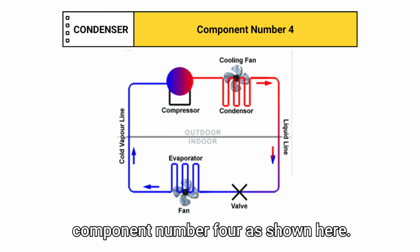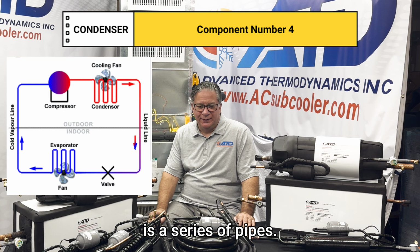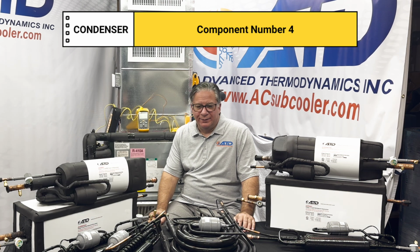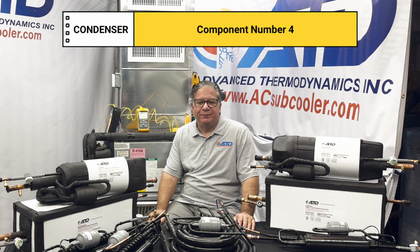The condenser, like the evaporator, is a series of pipes. Outside air is blowing across the condenser pipes, and heat is released to the outdoors. The heat released outside is the heat that was removed from your home via the evaporator coil.